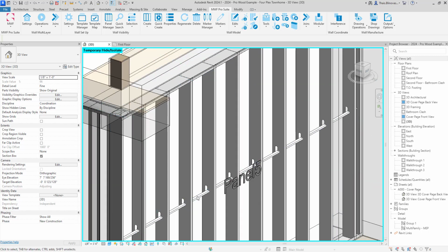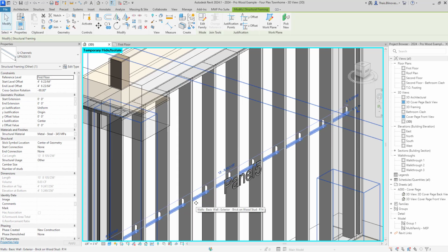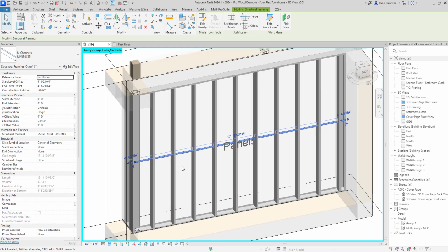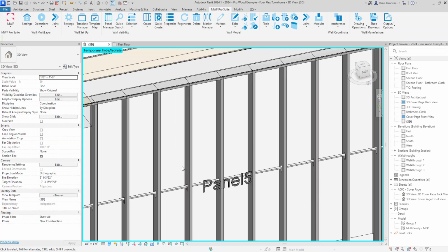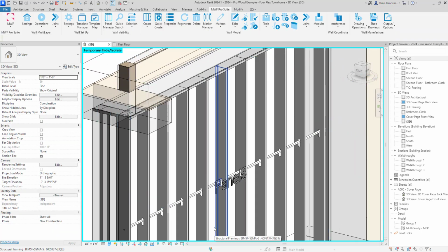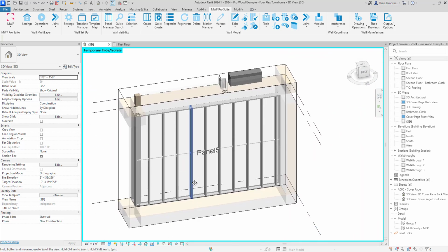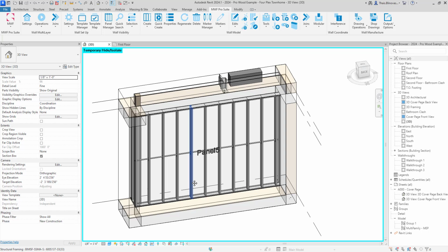Also, depending on the family and the parameters you have, maybe sometimes it could come out a little bit off. And in that case, because the punches are referring that particular member to get placed within the horizontals command, you might have to do a little adjustment in the whole series, and now you're actually able to do that within the horizontals command. Let me just do a Control Z so it looks nice. It doesn't look off center. But yeah, just to demonstrate what you could do with these two new options.